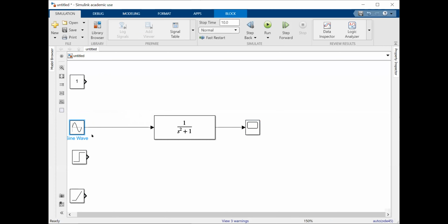Yes, that's fine. Depending upon the MATLAB version that you have, you could just have nums over dens. So x was x, yes. In the plot on x-axis, you have time. And please note, if you see that there is a capital T over there, T is equal to 10. That is the simulation time. And on y-axis, you have the displacement of the mass.